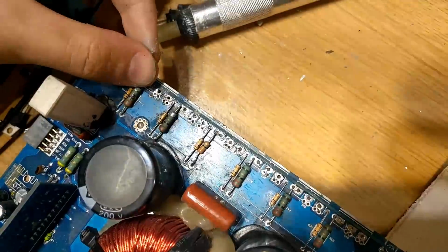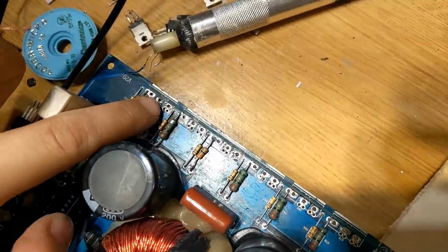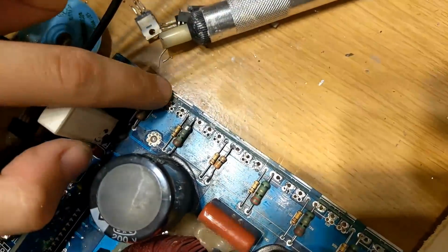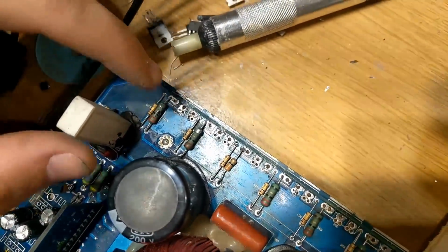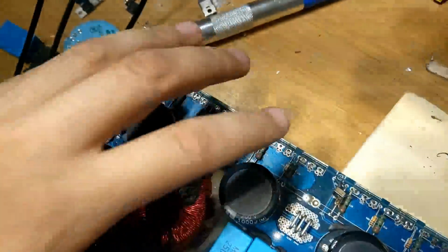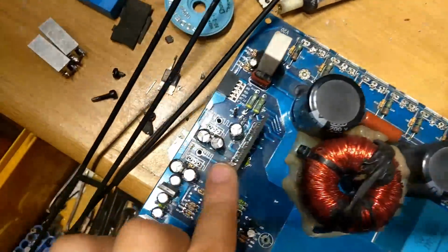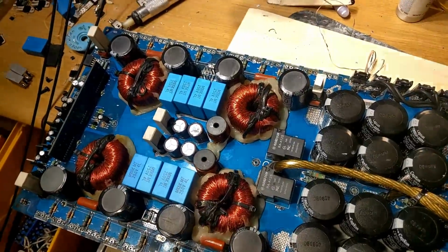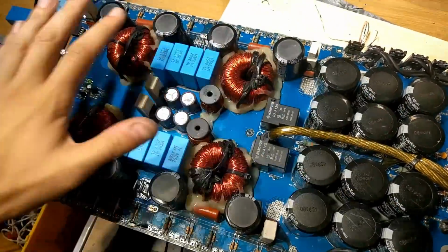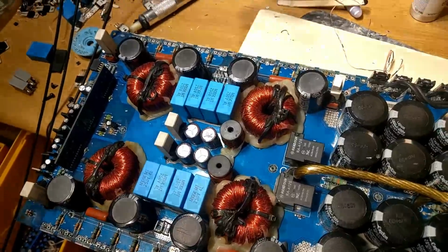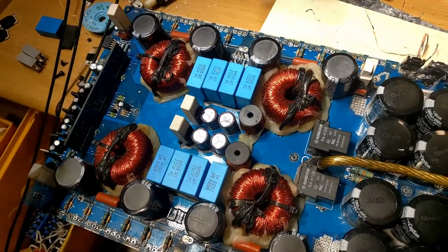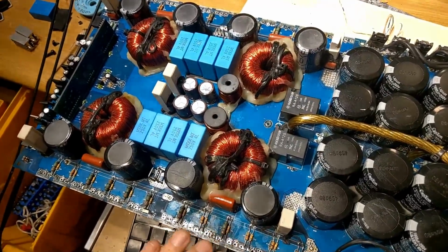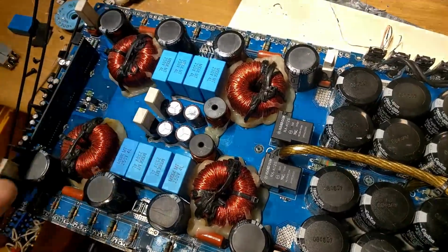So when that wire strand was floating around, it unfortunately touched the positive rail and touched a little bit of the trace here that didn't have insulation on it, and shorted out all of this bank of FETs. It completely exploded the drive IC on the driver card. So in order to get this back up and running, I thought it was a good idea just to replace the whole output section all in one go, because it's good practice. When the amp fails like this, it can send spikes to the others even if they read fine. So all output section MOSFETs are being replaced.